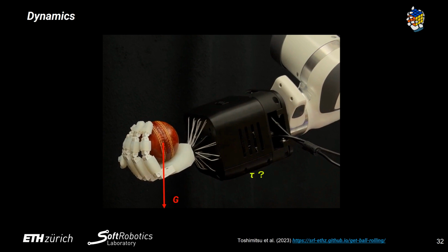So now we know how to map the position of the fingertips from the joint angles and further find the corresponding motor displacement. But for a hand to work, only position control is not enough. Proper force at fingertips is needed for holding an object. And for this, we need to be able to map the force needed at the fingertips to the motor torques. The Jacobians are needed for this purpose.